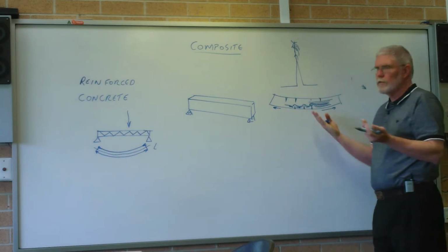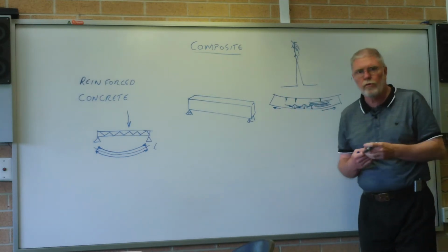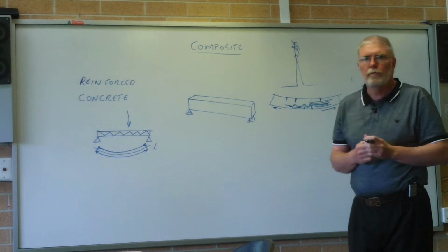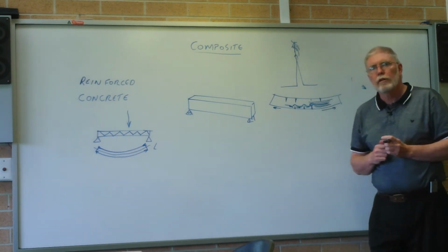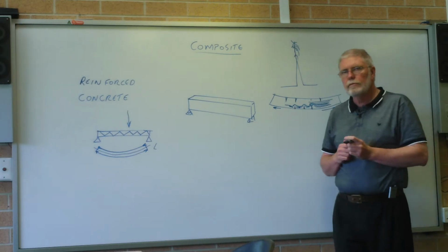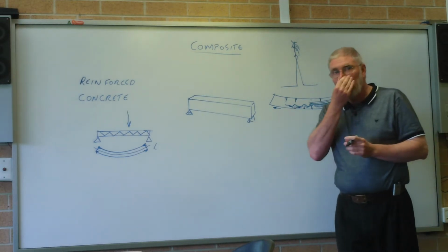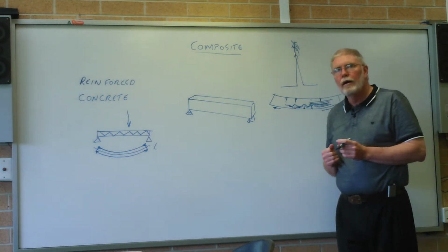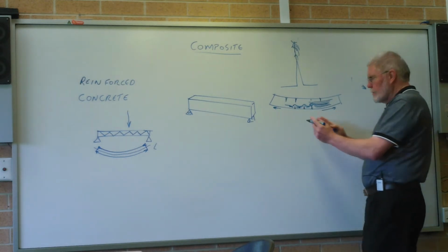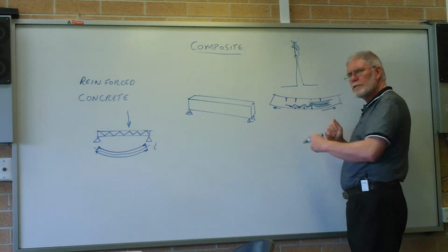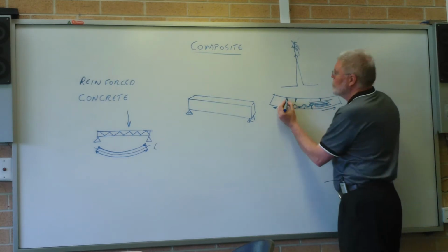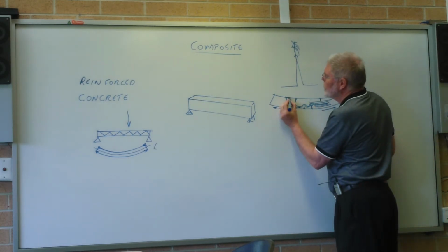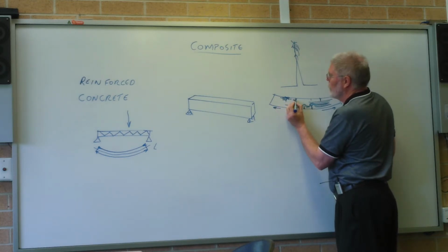Because I said there's cracks in the surface, you can't really make one without some form of problem in the surface. No surface is dead flat and perfect. You can try really hard. So what do you think is going to happen? Why would they spread? They're spreading down here. What are the guys at the top doing? They're closing. So now the surfaces of the crack are actually leaning on each other, and so the stress can be transferred directly across the crack.